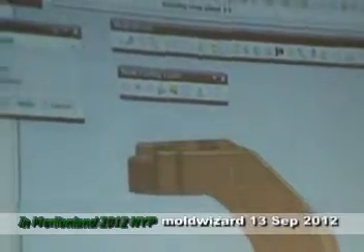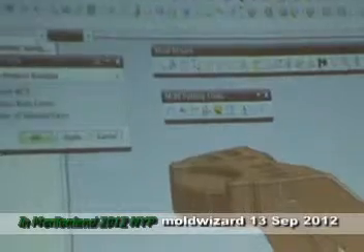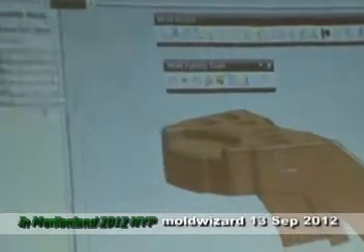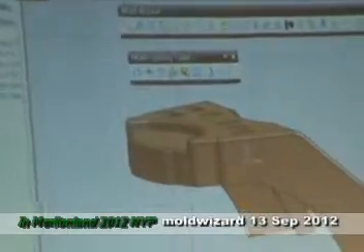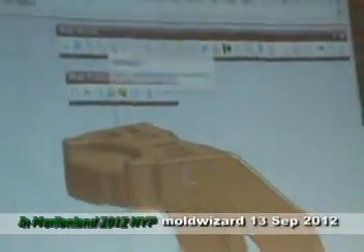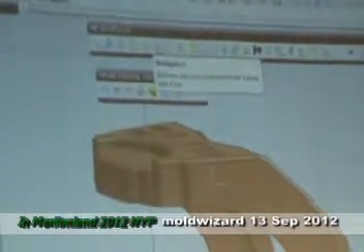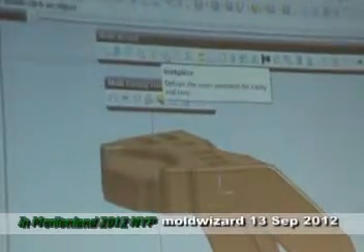If not, we can modify it. We can shift, we can rotate, then let the system remember using the WCS. You go to the next shrinkage, if you want to change. If you don't want to change, skip it. I already put in 1.005 just now, right? So skip it. Go to workpiece.